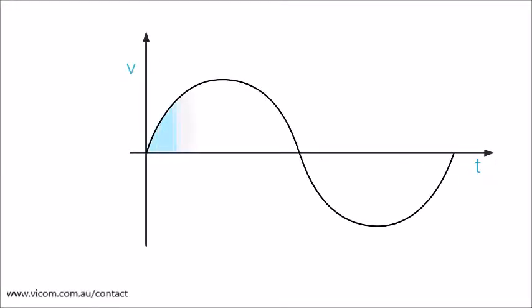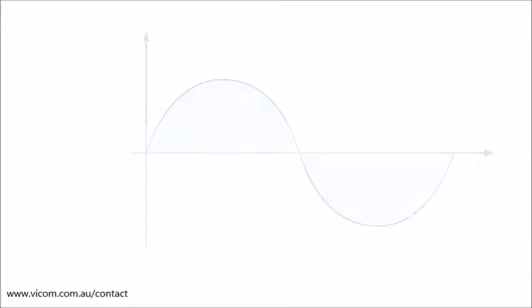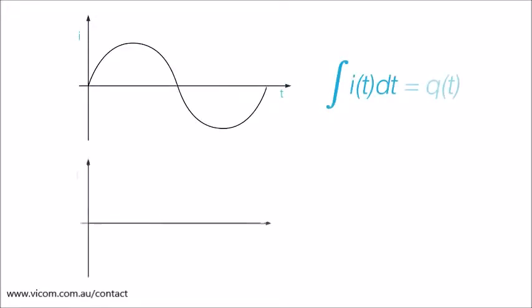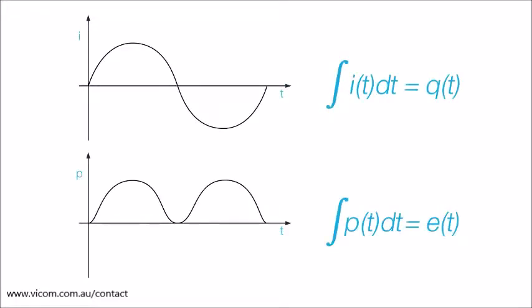Area measurements determine the area between the waveform and 0. It's computed by integrating the waveform over time. Areas can be positive or negative. Areas above 0 are positive and areas below 0 are negative. Area is useful for finding values that are integral functions of voltage, current, or power. For example, an area measurement on a current waveform represents the amount of charge delivered over time. Area measurement is also used with power waveforms to compute the energy delivered or consumed over time.